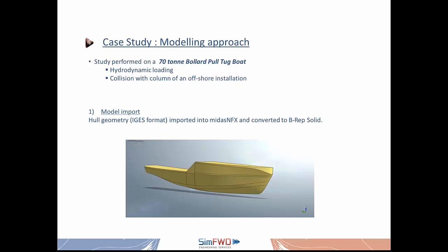So starting, of course, we have to import our model. We have used a given hull geometry. So Midas has the ability to import a variety of geometrical formats. One of them, and most used at the moment, is the IGS one, and we have used it to import it into Midas NFX.